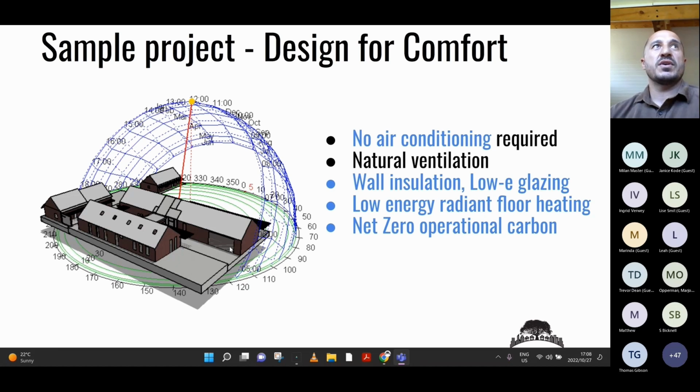I've worked in the UK where we made use of ground source heat pumps a bit. I've seen them used in the South African context, and you can achieve good efficiencies. Your efficiencies are often better than an air source heat pump. But the question of whether the additional cost warrants it is what you need to look at for each individual project. I don't know, Chilu, if you've got another comment on that.